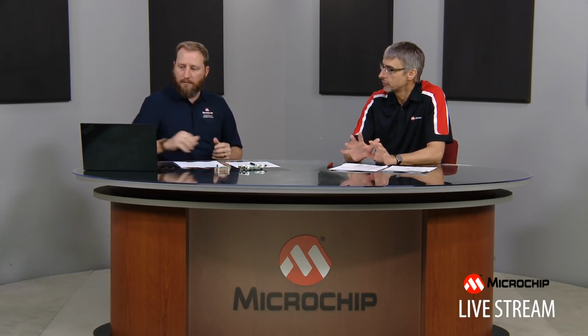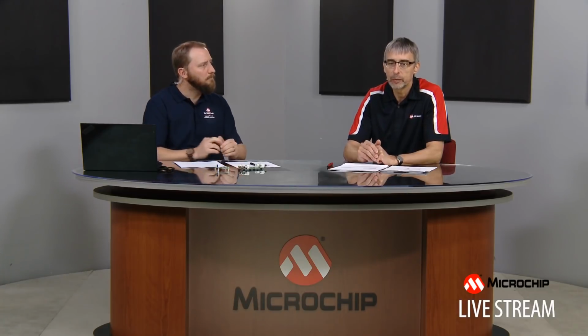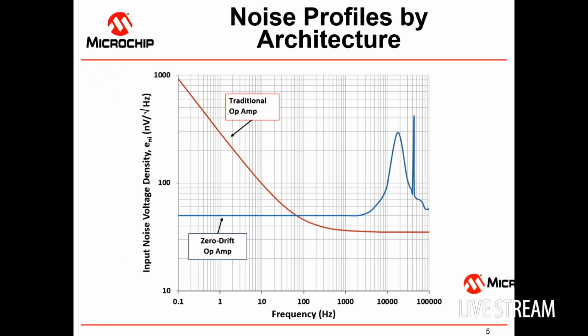And it's very important because that becomes one of the key features of zero drift amplifiers, especially as it applies to sensor signal applications where you have to deal with low level, low bandwidth type of signals. And to illustrate this a little bit better, we've prepared another slide to compare the noise profile of a traditional amplifier to the one of a zero drift.